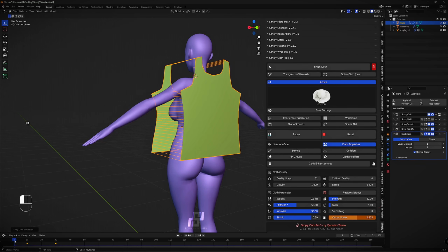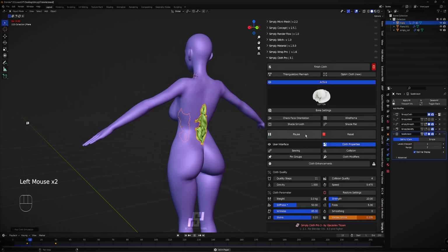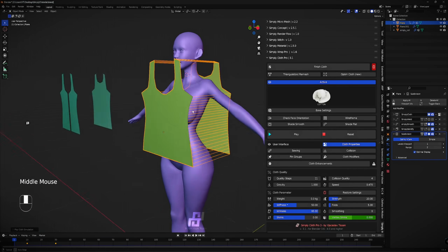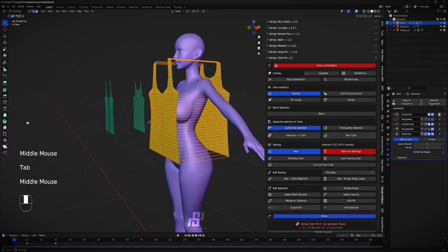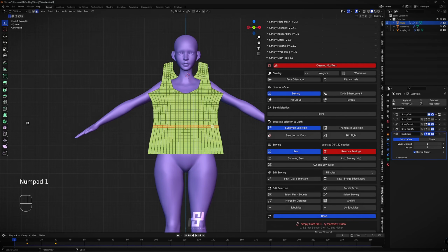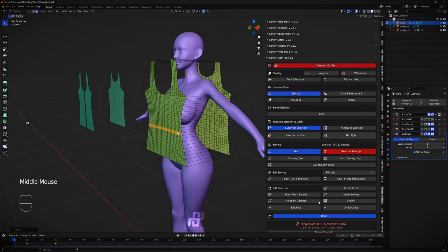You see, in the first frame it's shrinking, and then you try to simulate, and you get a full mess. I do not recommend using it that way. Use it slowly. Or if we want to have this tight, what I told you here, we can select this front part, activate proportional editing, connected only, and scale it in the X axis only, like this. Yeah, so like this we can test it.